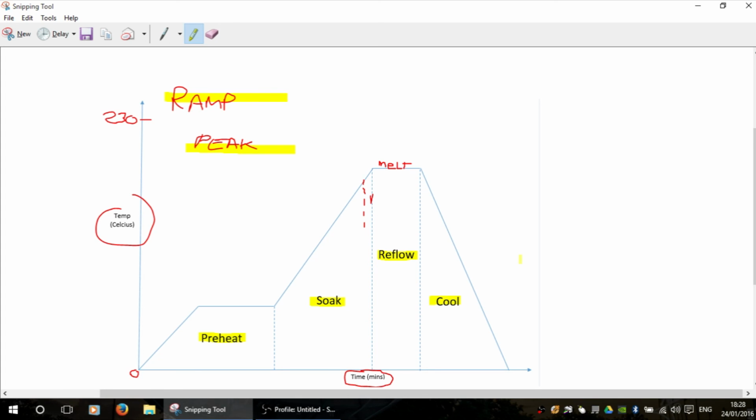If your chip itself has any integrated heat sinks, these need to be removed wherever possible. So if you're reworking PS3 BGAs, that needs to come off. Don't leave it on. PS4s or Xbox Ones, don't try to remove the exoskeletons, leave those on, but if it's got a proper integrated heatsink that pops off, then take it off. That will reduce any thermal stress, and either way, the thermal interface material underneath that IHS needs to be renewed anyway, because it doesn't respond particularly well to being overworked.